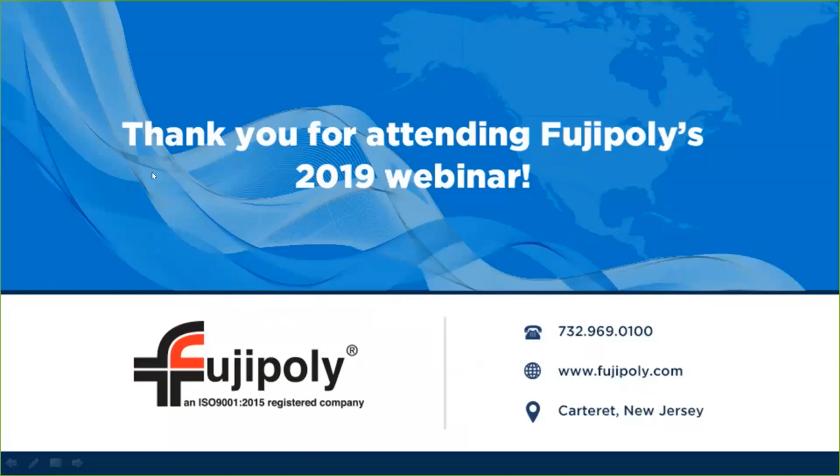And there's a question on whether a silicone oil extraction test is performed. We do perform Bellcore testing on all of our materials, which is available upon request. For further information, please send an email to info@fujipoly.com or contact one of us directly and we'll get you that data. Another question is, how do putty materials compare to the other Sarcon materials regarding silicone exuding or outgassing? Outgassing is actually very low. We test all of our materials to the NASA ASTM E595 test for outgassing, which measures total mass loss, condensable materials, and water vapor. It's well below the limits for all of those criteria.